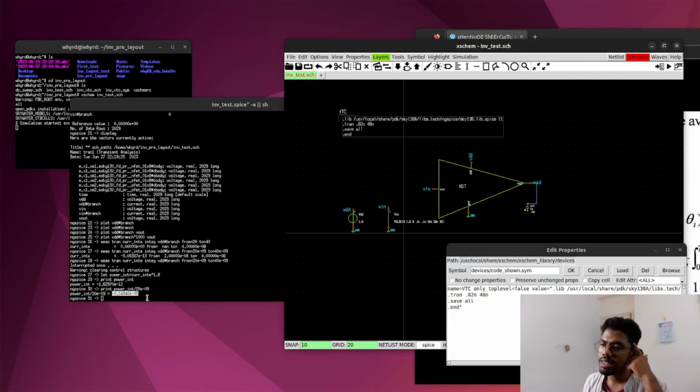But before that, see, this power dissipation is for one period, for one switching activity. So that means if we do the switching activity 5 times, then we will consume 5 times the power. So that means if we can reduce the switching activity, then we can reduce the power consumption, and there the architecture comes in.